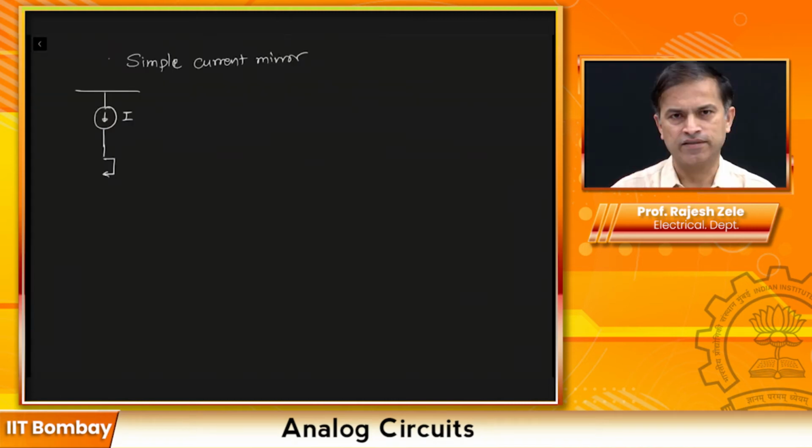Then what we do is we put it through a simple current mirror, which means a circuit that looks like this. Let me draw this completely. And so this would be your Vout, and this would be your Iout. Transistors M1 and M2. Okay, these are the two transistors, and there is a gate to source voltage of VGS over here. So the current source, this is VDD. The current source Iref, let's call it reference, it's coming from somewhere, and then we insert it into this diode connected device, VGS.